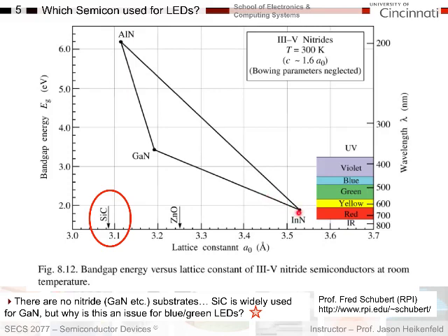Furthermore, going out to the red is simply not possible with gallium nitride, indium nitride systems. The diodes become very inefficient at that point. So then you switch to a different material system like aluminum gallium phosphide instead of nitride, which has band gaps over in this range, and has band gaps in the range of the red through the infrared.